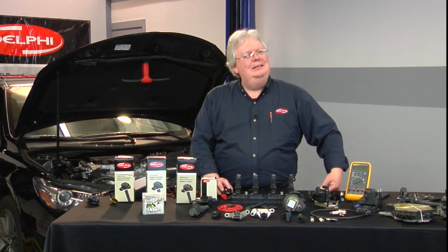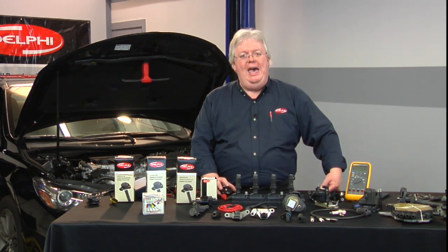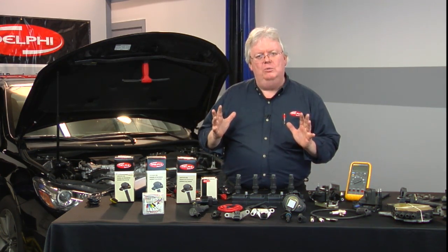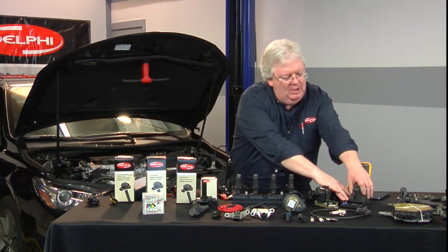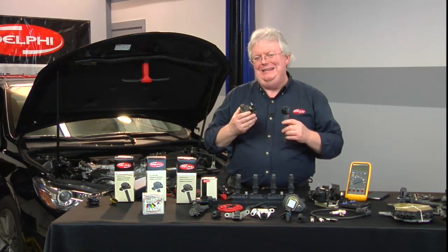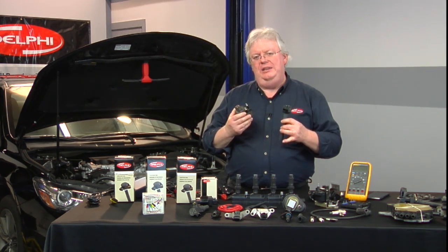All right, we got a man here interested to know, how can you detect or measure internal tracking on a Ford COP? That has always been an issue. In fact, some OEMs have had a specification of how long a coil, whether it be a DIS coil or a Coil-On-Plug, can withstand open secondary conditions before it starts tracking internally.